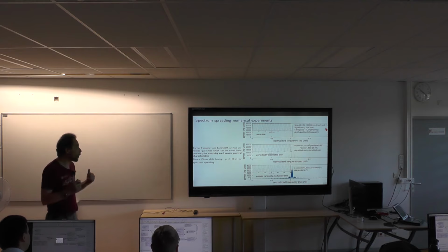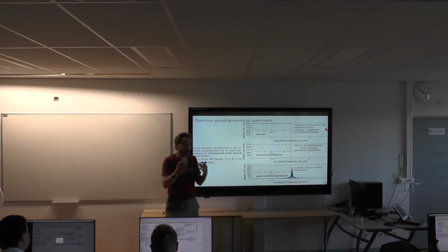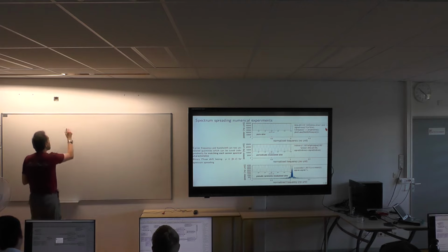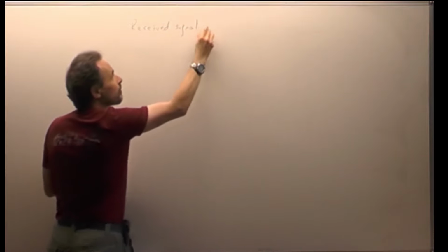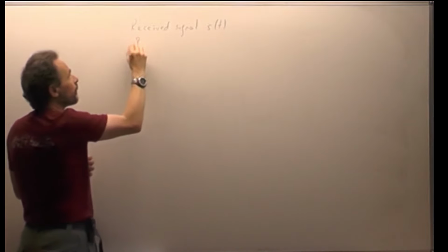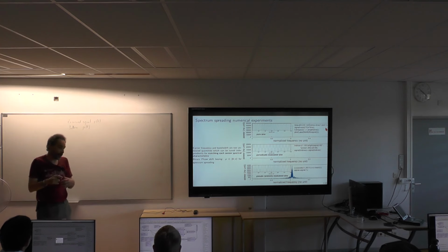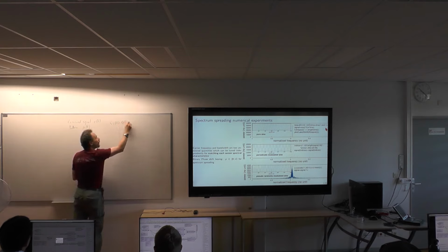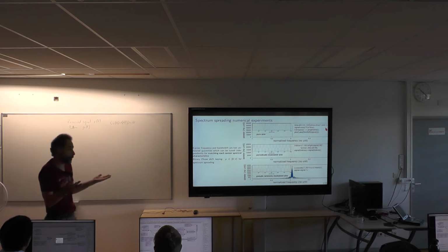So now we said we're going to imprint these random sequences of phases on the carrier, but the question is, on the receiver side, how am I going to recover this pattern? I receive a signal S of t, and I've broadcast a pattern that I call P of t. How can I detect this pattern in the received signal? Let us assume, which makes everything much easier, that the mean values of S and P are 0.